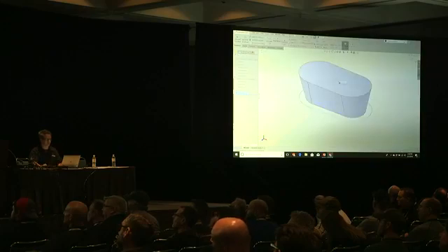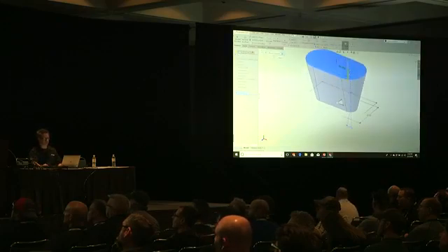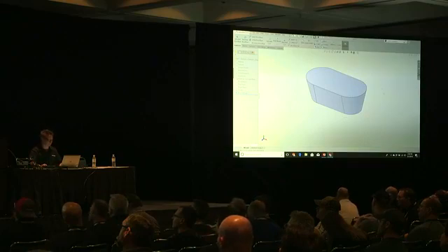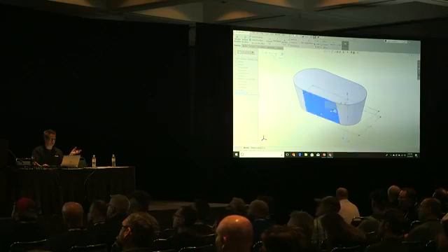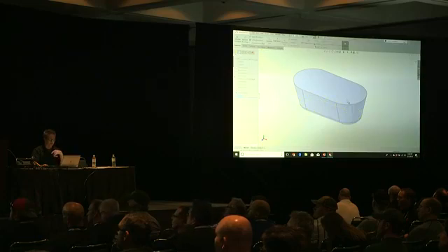The reason I did that is because now I can grab this and change it however I want, and it's going to stay attached to the floor. This gets into paying attention to your cursor. I'm going to click right here, pop up, select other, click right here, pop up, there's my fillet. I'm going to type in 3, hit enter, right click, didn't move my mouse at all.